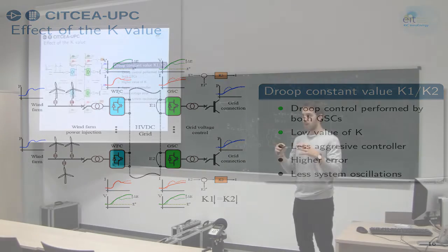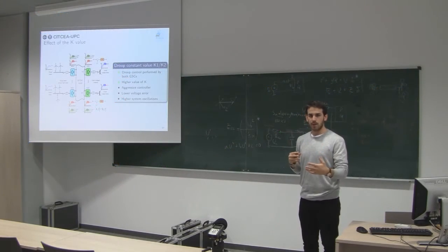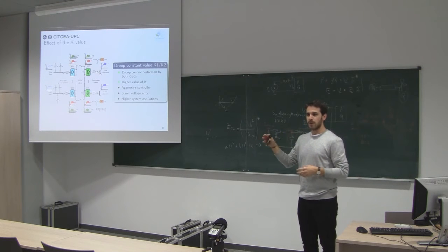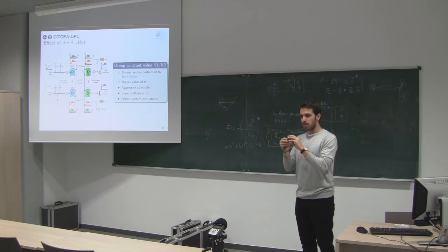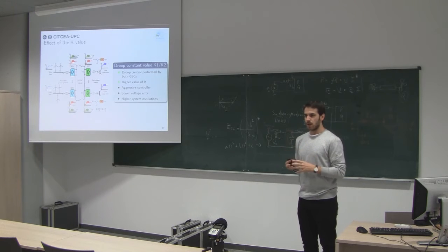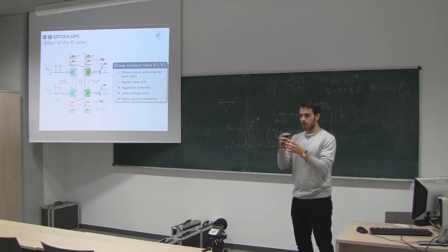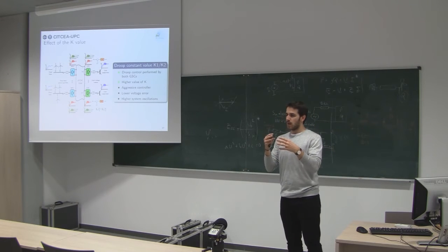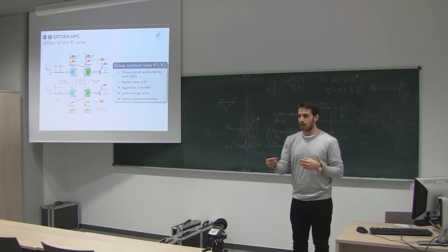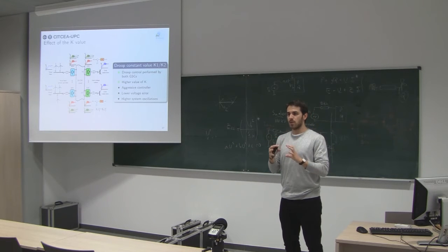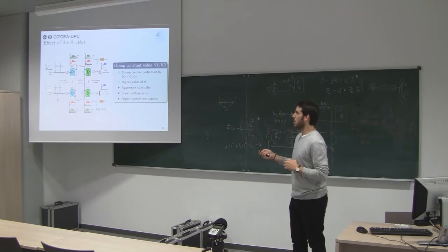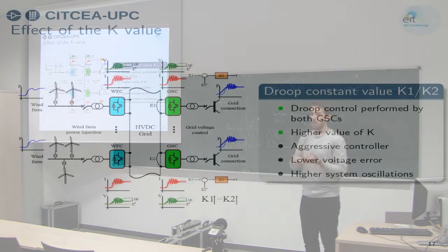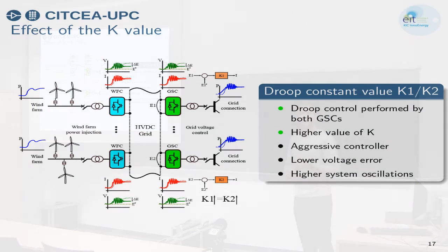You have to consider parasitic reactances and inductances of the cables, because the core of the cable with the screen has leakage inductances, and there are parasitic resistances to the earth. So it's quite complicated, and those combinations of resistors, reactances, and capacitors have resonances. If we create an aggressive controller, we can excite those frequencies and see oscillations, which are of course not desirable, because if we have a huge oscillation in current, we can break the IGBTs, the converters, and damage cables.